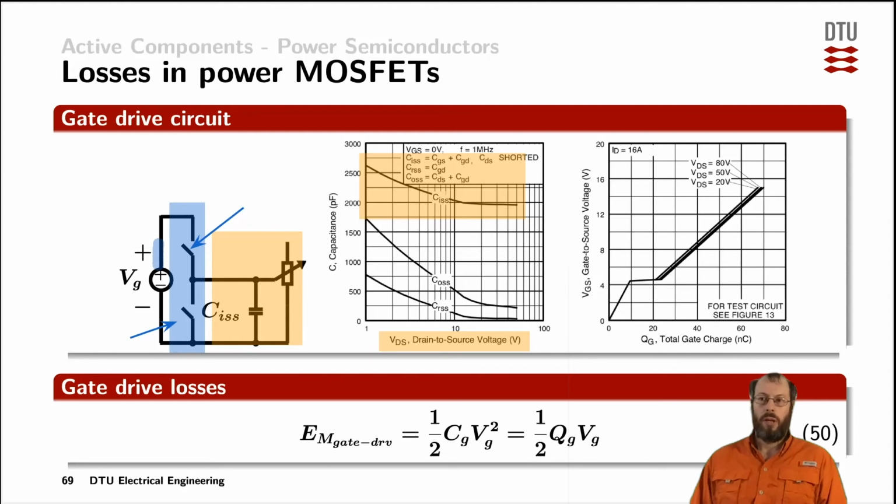Whenever we turn on the power MOSFET, we conduct current through the high side device in the gate driver, charge the input capacitance of the MOSFET, and that current returns to its source. For turning off the power MOSFET, we retract those charges into the low side of the totem pole driver and burn the energy in the on resistance of the low side transistor in the totem pole configuration.